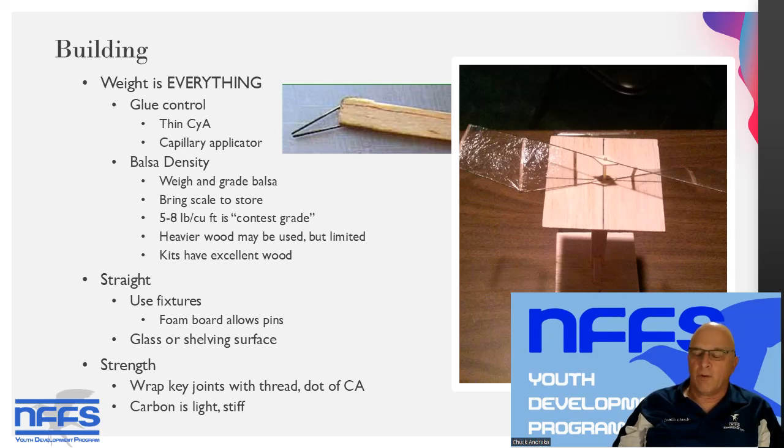Balsa density is important. If you're going to do your own design, weigh and grade your balsa. You can calculate your pounds per cubic foot, which is how we normally grade balsa, by weighing the whole sheet on your gram scale and then calculating the density of the wood. I bring my scale to the store whenever I buy balsa. If you go in a Hobby Lobby, you may not find any lightweight wood, or you may find one sheet out of the whole stack.